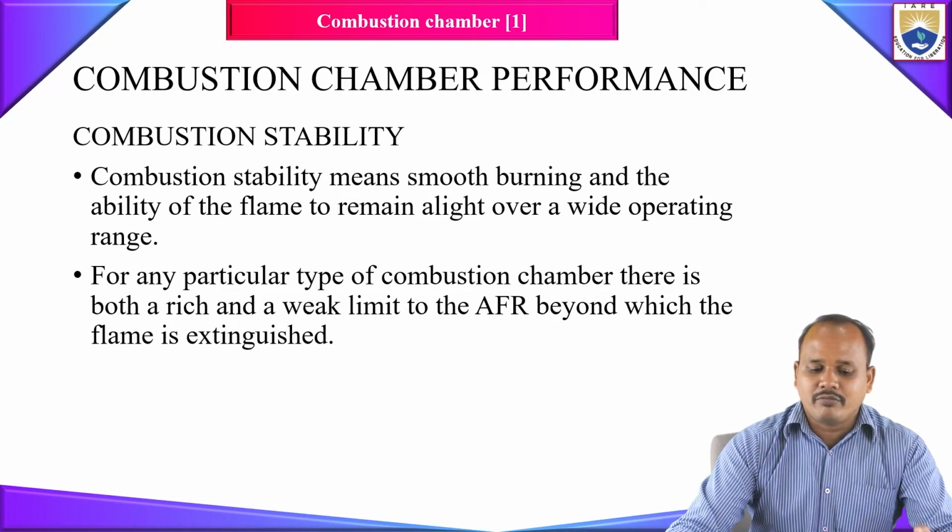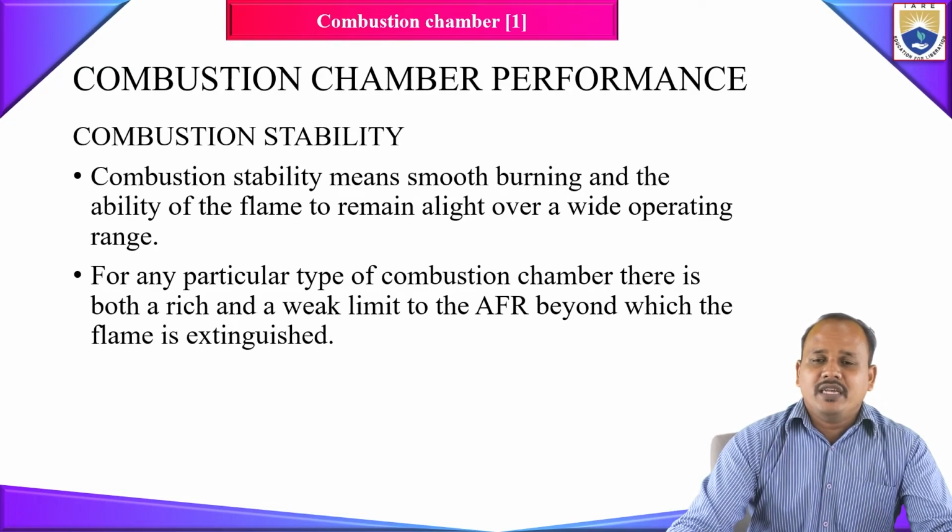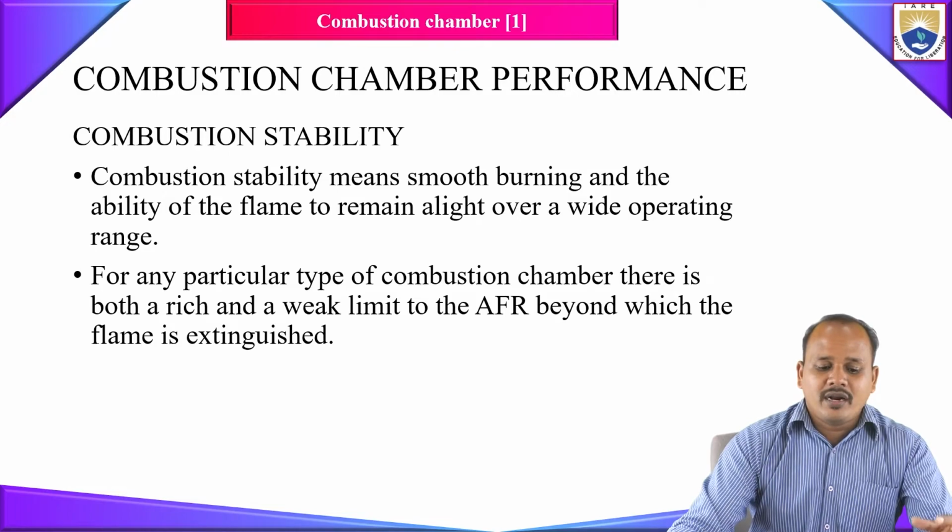This is a very important parameter, because even if your efficiency is maximum, even if the loss happening inside your combustion chamber is very small, if the operating range for stable combustion is small, it is going to limit the application of that particular engine. So when you are designing an engine, the combustion should be stable for a wide range of operating conditions.